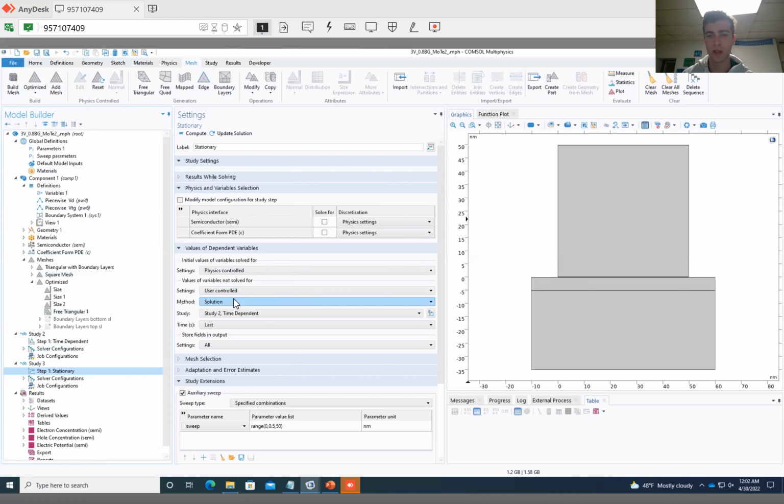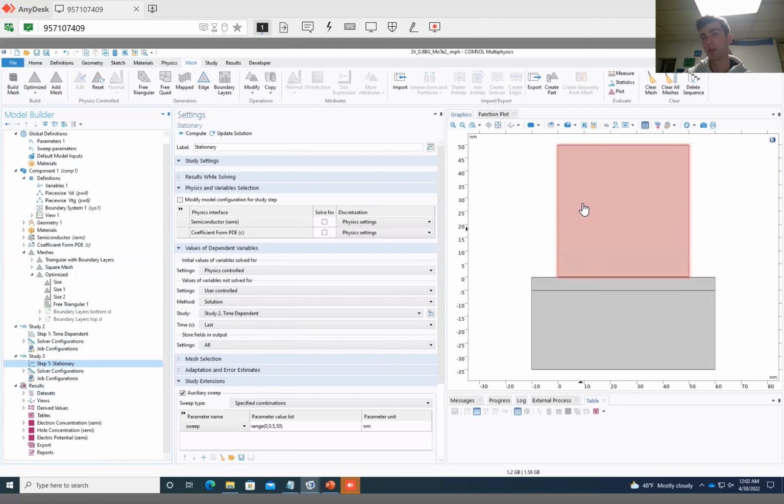So I'm going to briefly explain our post-processing system here. Basically, when we solve for the values here, like for instance the ion concentration in our electrolyte, it'll give us the concentration of our ions in terms of per meter cubed, which is great, but that's not really useful for comparing to literature. We would like per centimeter squared to compare for sheet carrier densities and sheet ion densities.